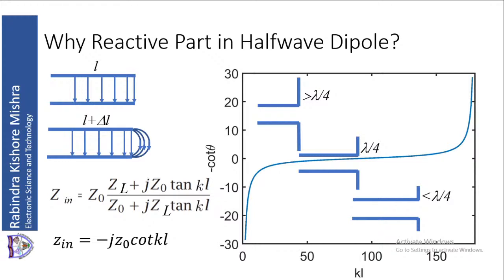There is an energy storage. Because there is some energy storage, there is a loading, reactive loading on the antenna. Since there is a reactive loading on the antenna, that is changing its resonant frequency. So its resonant frequency will be something different from the designed resonant frequency. So to consider these effects, first is we must know why this is happening. Then we can use our own reasoning to decide how to compensate for these things.